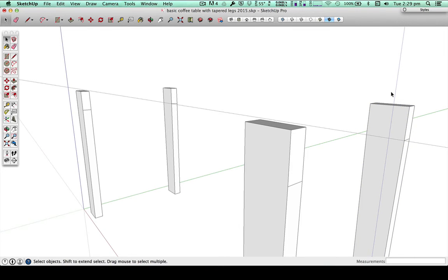I won't delve into exactly why it's an issue, but for now, let's just get ahead and start drawing our skirt piece of timber. So I'm just going to click and let SketchUp find the points for me, because we know this is 25 by 60. And when I do that, you can see now I've got a solid face on the group. I'm going to hit P and just drag that.